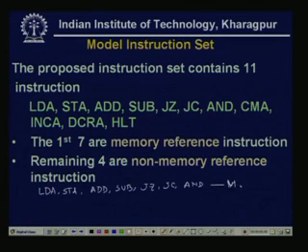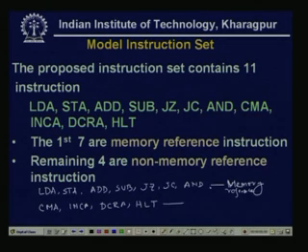Memory reference instruction means they all require a memory address. But the remaining 4, the complement, the increment, the decrement and the halt, do not need any memory address, so they are non-memory reference. Normally, all instructions can be divided into these 2 categories.